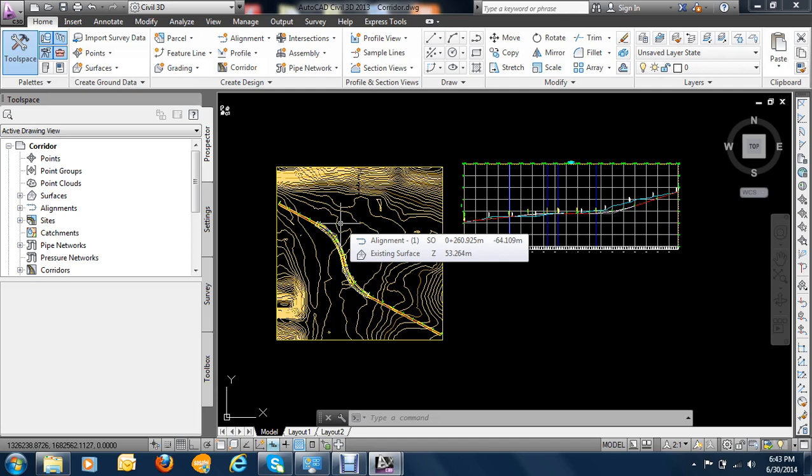I'll just show you how you can do it. I'll just do it one way. If it's two ways, it means you have to increase the lane width. If it was going to one side, it's 3.5 that we use.